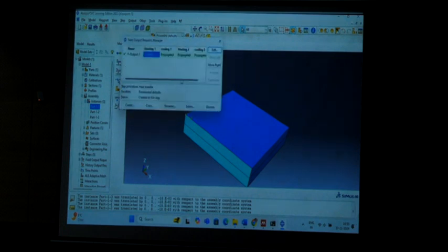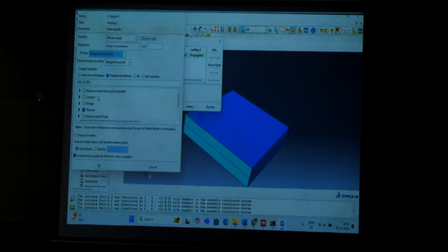If you can see it here, it was all created and all these are propagated. And go to the edit option. Here we are going to give the option like which one we are working on. Since it is a heat transfer, it was automatically pre-selected by default, it will take the thermal option. So we're going to check the nodal temperature, heat flux vector, and reaction fluxes, whatever the things it will be. Just click OK.